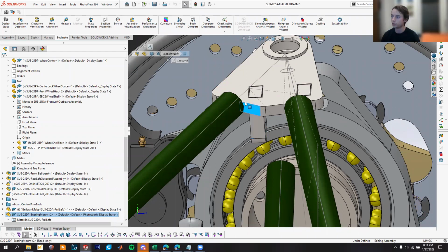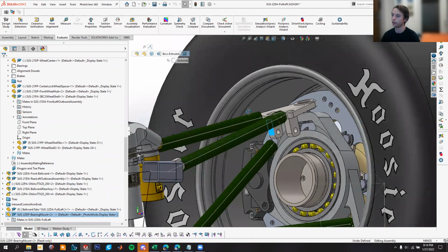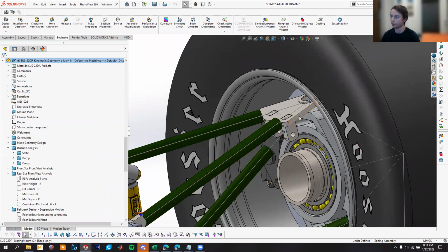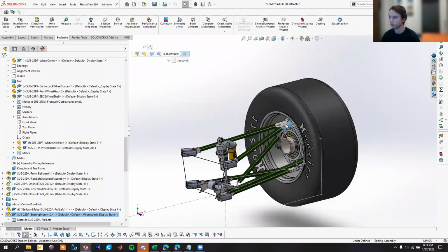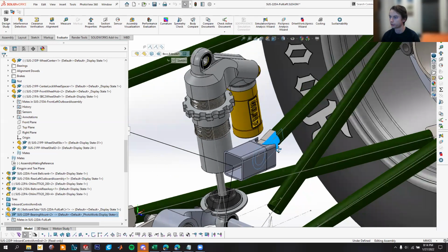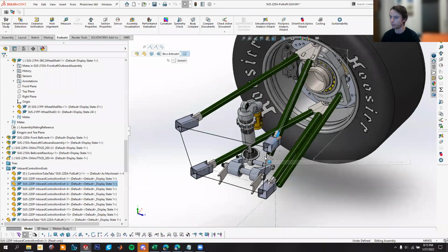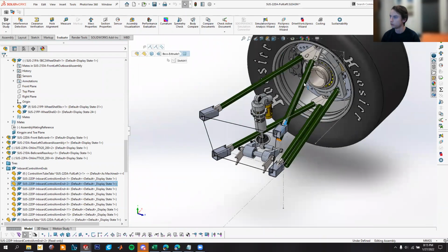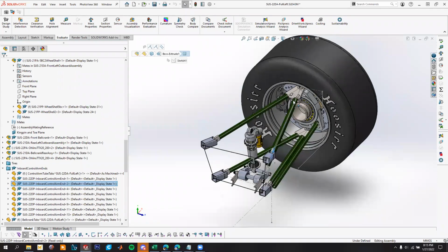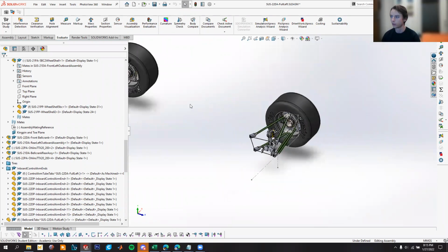Okay, so the main body part still needs to be thicker to accommodate that thicker bearing, but these tabs can definitely go thinner than this material just to reduce weight in our unsprung. So they can become this 1/4-inch steel thickness. Cool. Awesome.